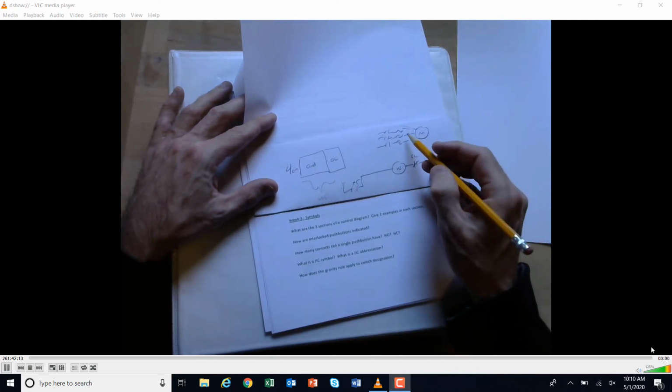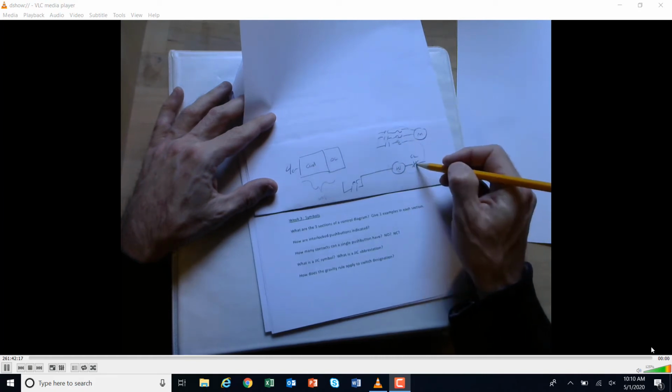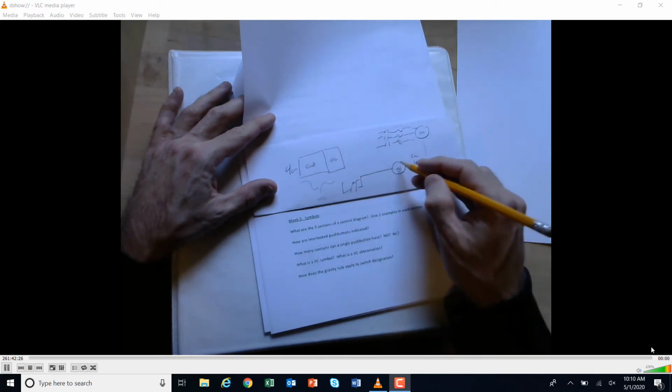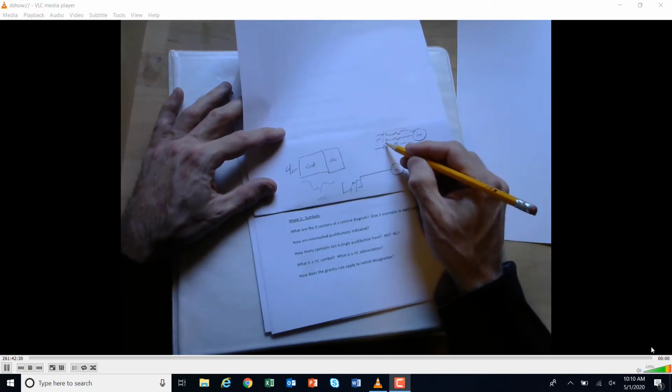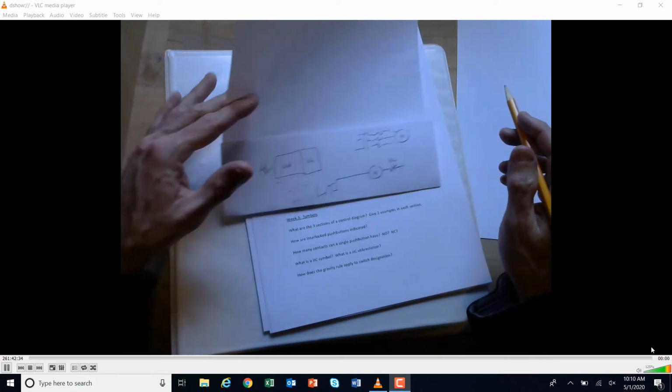Okay? And we use some sensor here. This sensor would break the continuity or remove voltage to the motor starter in the control circuit. The motor starter would then open up the power circuit. So that's the difference between my control circuit here and my power circuit. Okay.